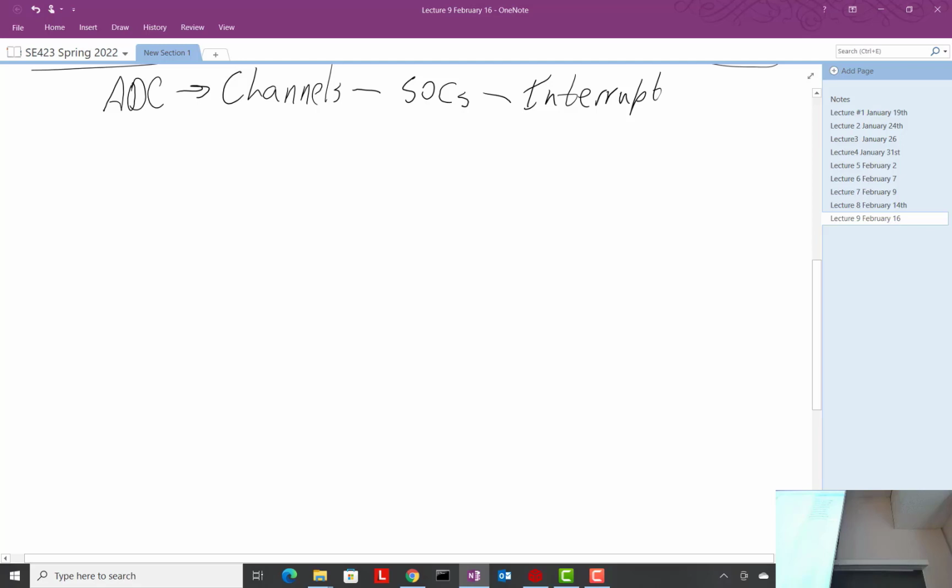The maximum voltage is actually 3.0 volts on this processor. Some will take the DAC all the way; some processors go up to 3.3 volts. You can buy DACs that go from minus 10 to 10 volts, but that's another story. Our DAC goes between 0 volts and 3 volts, and there are 4,095 different voltages in that range that we can output.